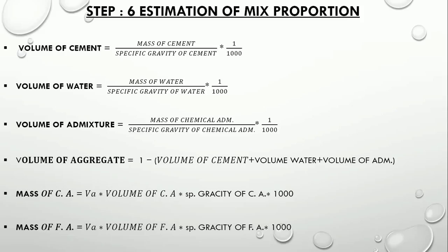So guys, after this, we can give the proportion, that is, what proportion is required for achieving the required strength of the concrete. And we can state it in proportion like 1:1.5:3 or other, that we had calculated from here. So it is the basic concept or basic process that we have to follow for the concrete mix design. And here, we finish the concrete mix design.